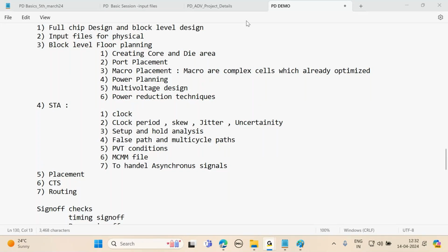You have your own project that you will bring, but you should get the netlist or the RTL. You can ask the admin to load it on the server. We are not going to give you the tool outside; everything you do is on the server only. You can ask the admin to load the RTL, synthesize that RTL, and then do the physical design. Your design will be very simple because it will not have any macros. If a design has no macros, it's very simple; only if it has macros is it very complex. You can do it on the server, the same steps that we are doing.